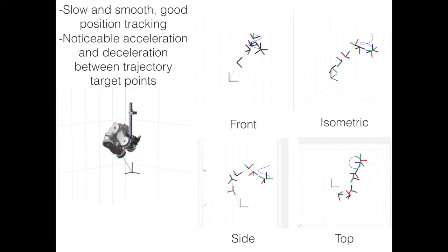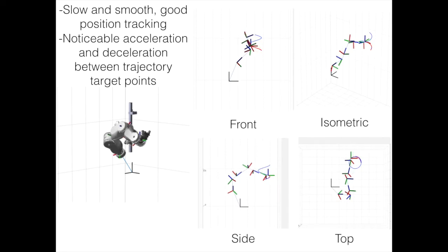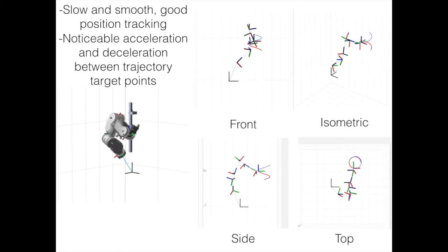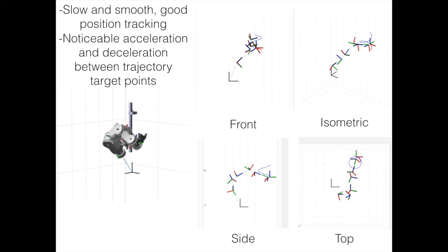Without disturbances, however, n did not have too great of an effect on the accuracy of the tracking. Decreasing the cost on input torques predictably would increase the acceleration of the arm and allow it to travel along the trajectory much faster. Sometimes, this led to a little wobbliness or other loss of accuracy in tracking, which was also to be expected. In the end, we decided to maintain higher values of R because decreasing the amount of acceleration of the arm also aligned well with the safety goals of our controller design.